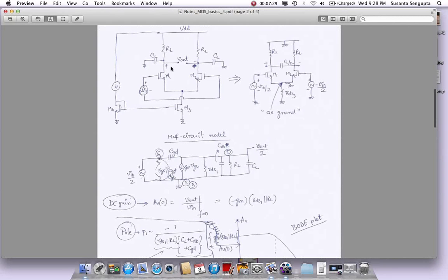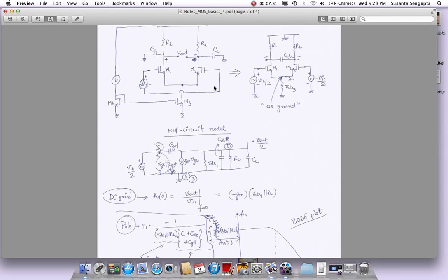One of the ways the 0 comes is, as the definition says, the output has a 0, meaning at that point the output is 0. How can the output be 0? One of the ways it comes is when you find two paths from input to output. If the signal could flow through two paths, then the summation of the two paths could cause a 0 at the output.